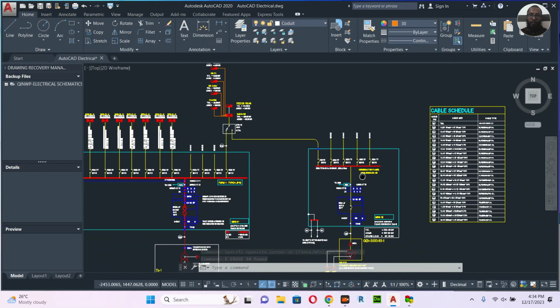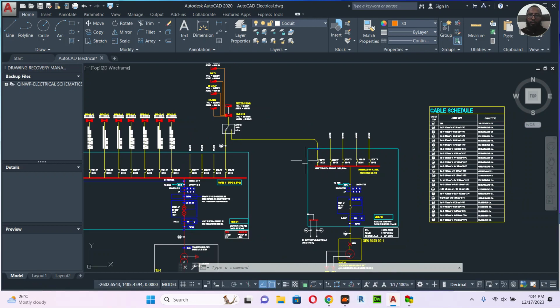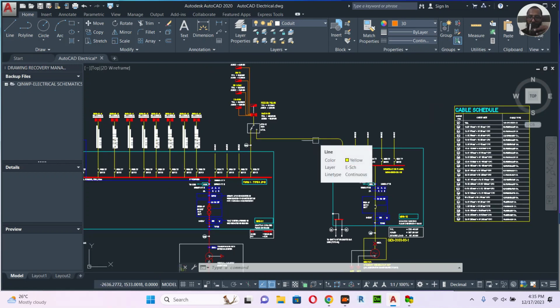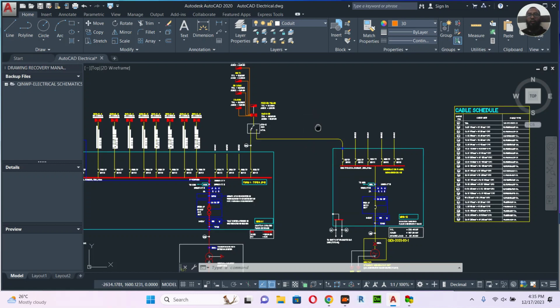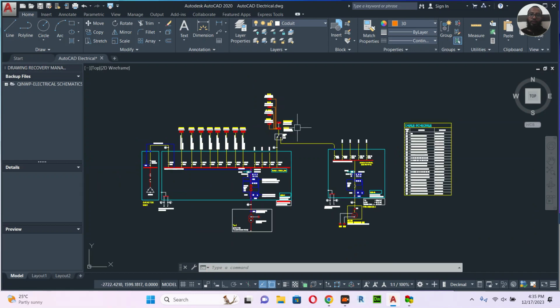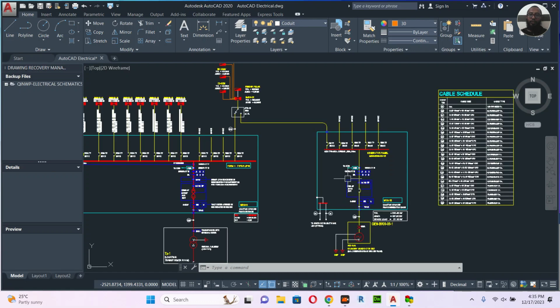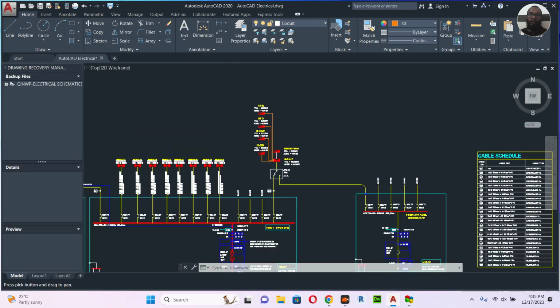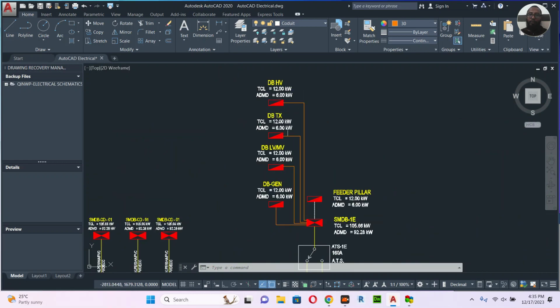Another concept, they put it only for the lights. So for some lights, there is an emergency light. An individual light will have a 3 hour battery backup. So in case of power failure, that battery backup will start to work, and then the light will work for up to 3 hours. But here it's giving power to the panel, so whatever is connected to the panel will work.